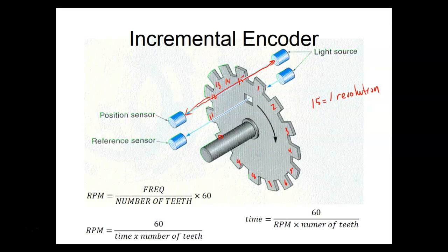So what we'll do is, if I can do the time between one pulse, so we get a pulse for every one of these, we'll get a pulse out. Now, of course, if this is an incremental encoder, if this is a through the beam, then every time a blade comes around, we would get one of these. And they would be at a constant rate if the motor is running at a constant speed.